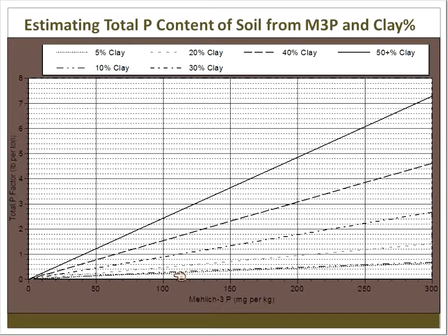Where do we get the most erosion in North Carolina? It's on our more clay texture soils that tend to contain more phosphorus. And so by knowing how much soil we're losing, knowing the approximate clay concentration of our soil, which we get from our soil mapping unit, the North Carolina PLAT program determines automatically how much phosphorus is lost from erosion. Now the nice thing for you, the user, is that all you need to know in order to calculate this is what county you're in, what your predominant soil mapping unit is, and what your erosion rate is.